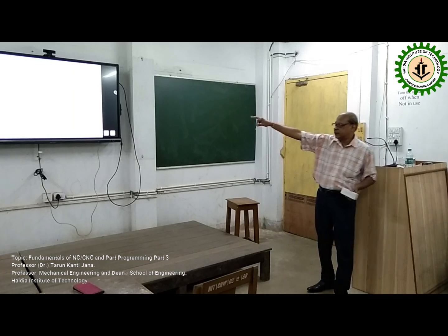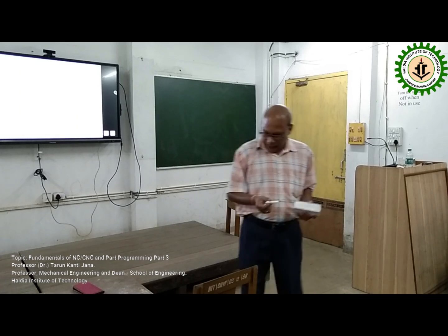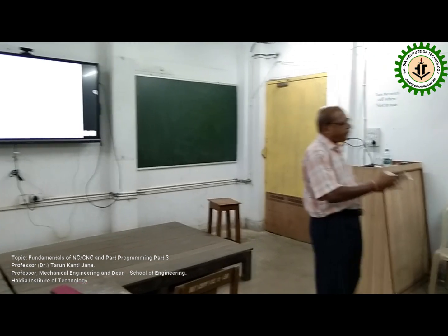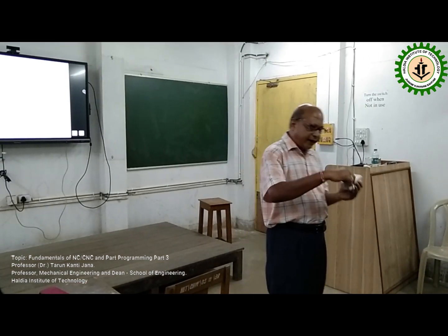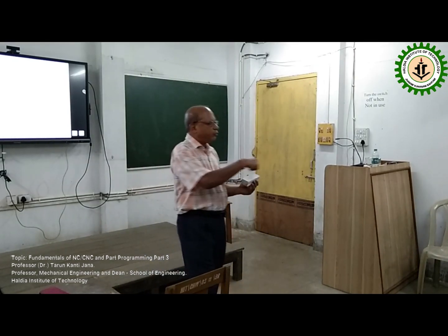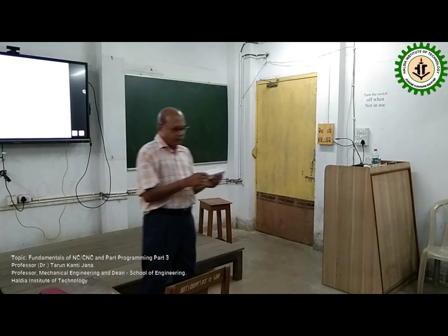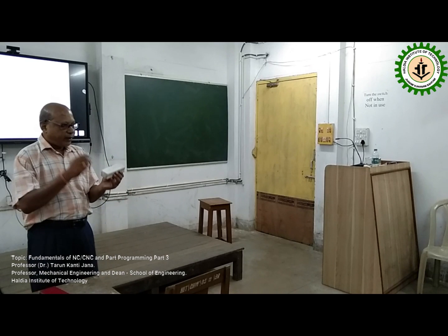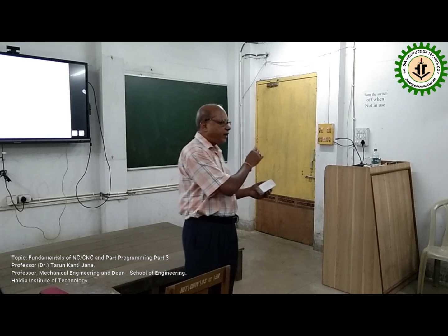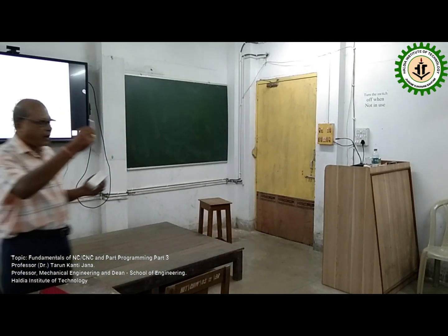Now, in the bracket I have mentioned the acronym CRC. What is cutter radius compensation? Now, suppose this particular job will be carried out in large number, maybe 10. Suppose one cutter can take care of 5 or 6 jobs, after which it needs to be replaced. Suppose I carry out 2 jobs. Now, it may so happen that there will be accidental damage, or in the course of time there will be wear. Now, by replacing this cutter with another cutter, it may so happen the same cutter is not available. The cutter which is available is of different dimension.